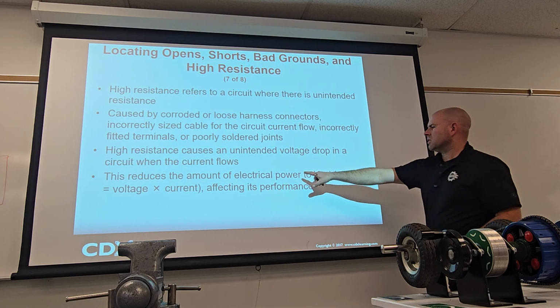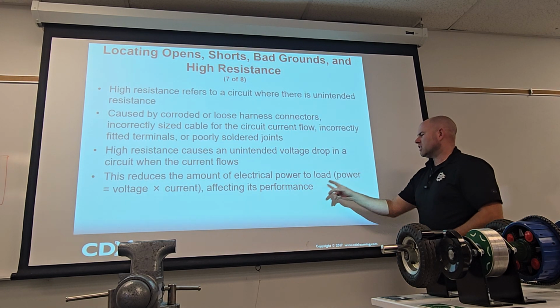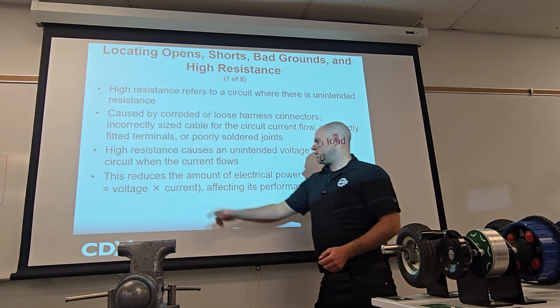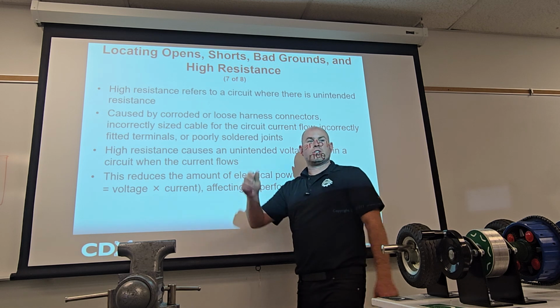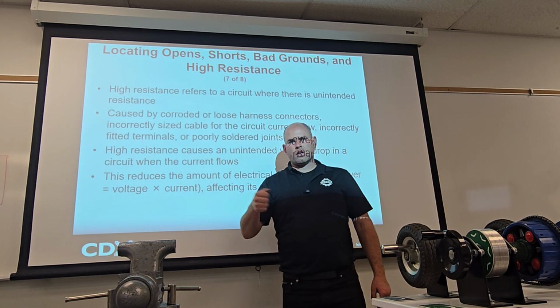And so again, that unwanted resistance will cause unintended voltage drop, which will reduce the current flow. And that becomes less power, because remember, power is voltage times current. So that affects its performance. That's why your motor's slow. Or your starter too. You know, like you got to start the car. The starter goes.